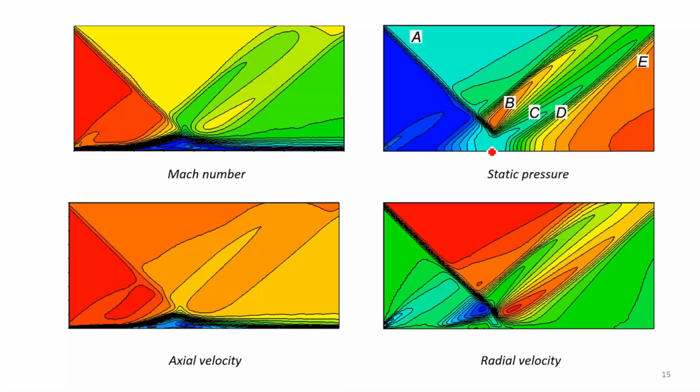one important aspect which I explained to you in one of the previous lectures is the zero pressure gradient on the surface of a wall. Since we have a boundary layer, all pressure lines are perpendicular to the surface. Approximately perpendicular, because this visualization is from a triangular mesh, so it was made as an approximation of the results.